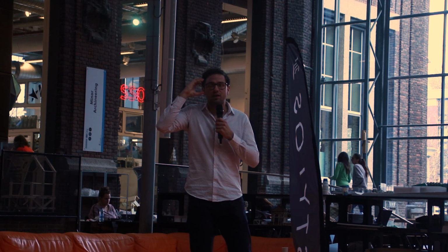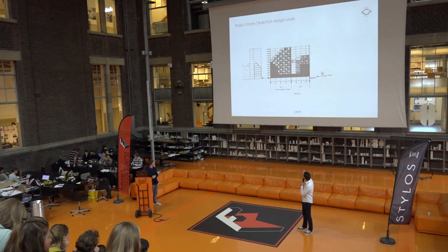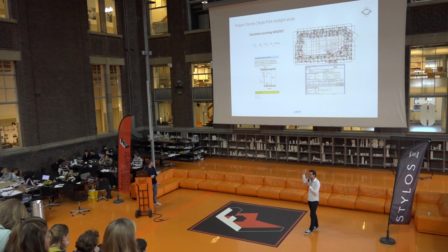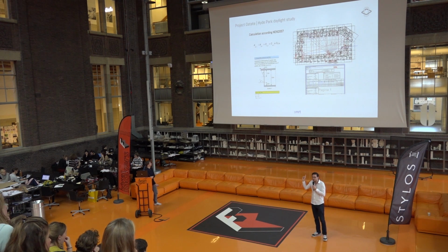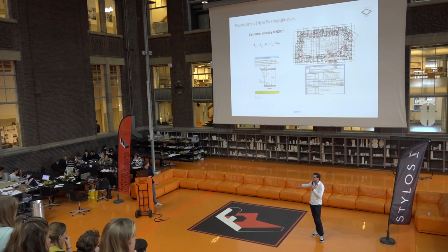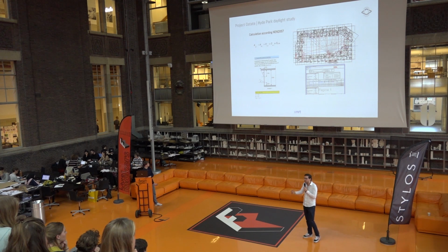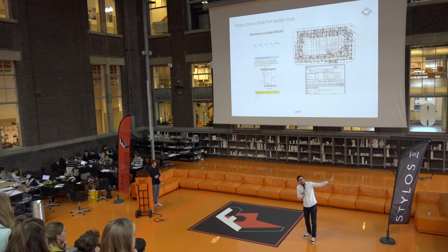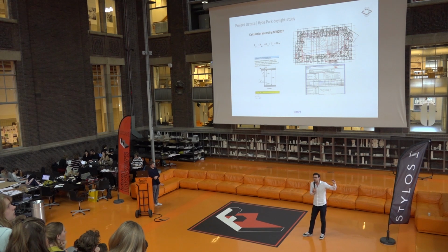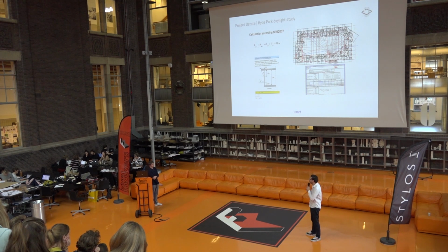But Snippen asked, okay guys, we know there's not much coming in, and we want to have good quality indoors. So can you calculate this? Well, okay, we will do that in a traditional way. That was the first question. This is the traditional way. You have to see how high the upper side of the building is, and how much blockage there is for your own window. So you have to deduce some sort of quality factor: the window is this size, but actually only this small part will have light coming through. That's what you calculate according to the code.